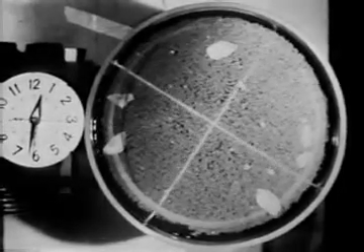When a fluid flows around a sharp edge, viscous forces in the boundary layer produce a separated flow. The fluid which has been affected by concentrated viscous forces forms a concentrated vortex. We can make the strength of a vortex visible by a ping-pong ball which remains in the dimple. The rate of spin, though, decreases because of viscosity, which spreads the vorticity of the core into the surrounding fluid.